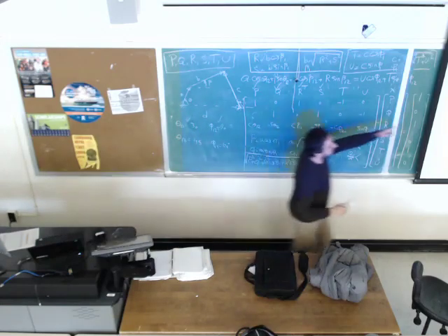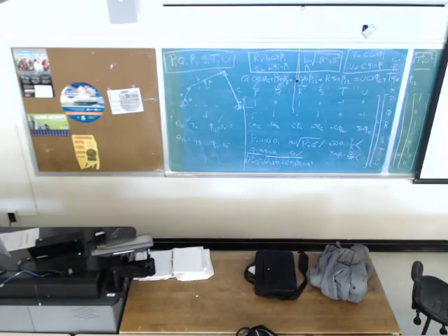So at this point, going by negative 52 point something, which is almost 53, draw a line and go by this length, B, 1.42. You end up at this point. If you connect this to O4, this length must be 0.431, and this angle must be negative 34.3. So this is the mechanism at the first position point.